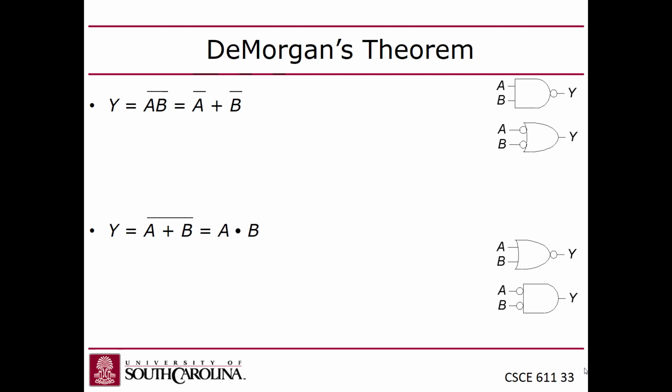But the interesting thing about these rules is that you can use them to simplify logic, but you can also use them to change it. I mentioned the sum of products. If you do sum of products form, you may end up with a simplified expression, but you may not be able to implement it directly in your logic because you may not have gates with enough inputs to directly map your sum of products form onto the hardware.